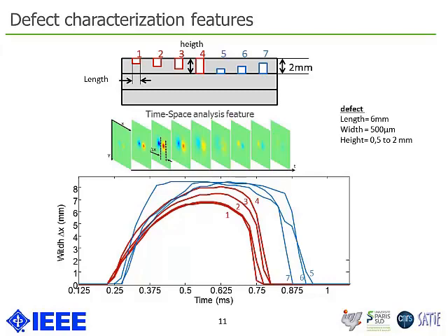This diameter, called delta x here, you can follow its evolution during time, and you can see that for the surface defect, you obtain this red evolution of the diameter with a synchronized rising time and a desynchronized falling time, and various amplitudes that are reached. Now for a buried defect, you can see that it's completely another story. You have delayed rising time, delayed falling time, and also you can see that all the amplitudes are the same, which translates the fact that the defects are reaching the same depth within the material.